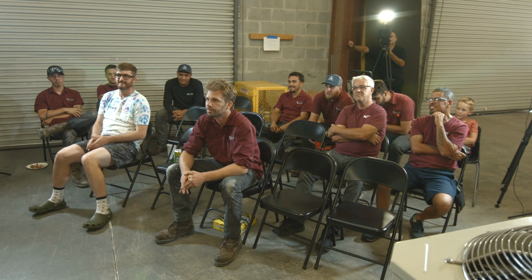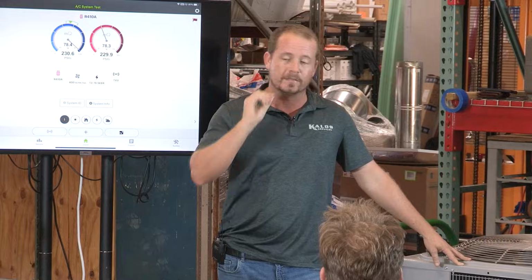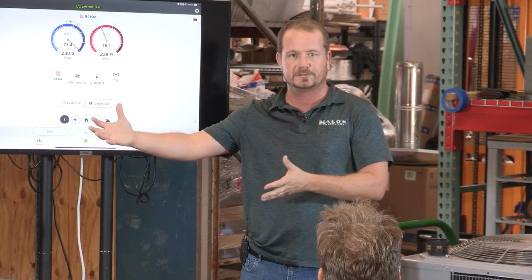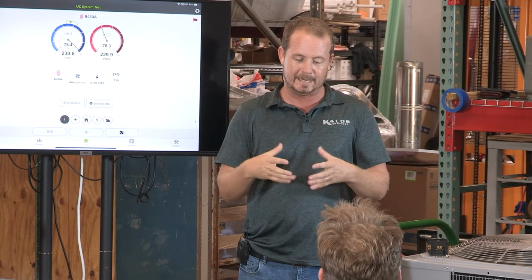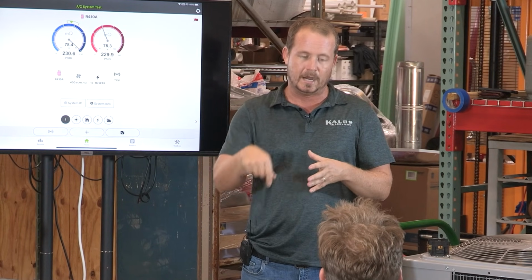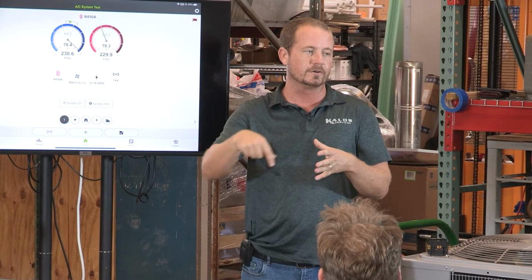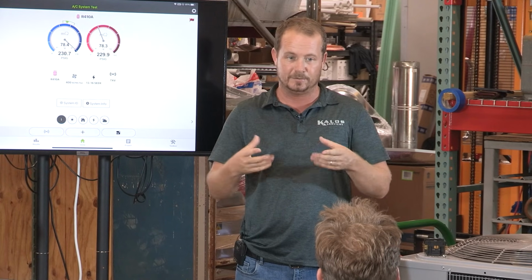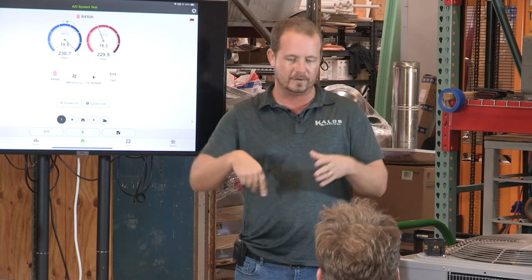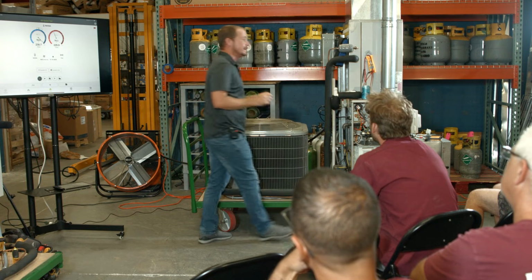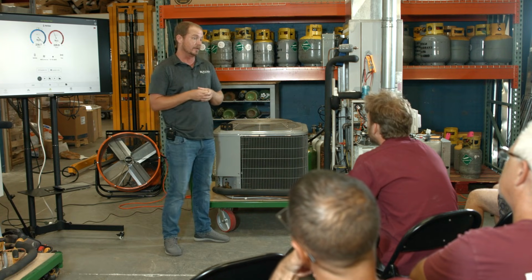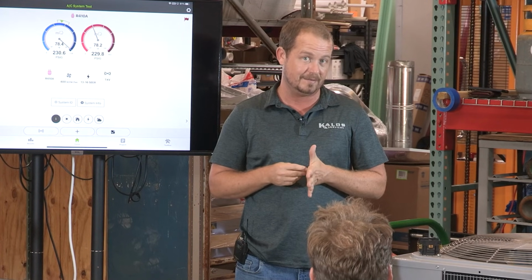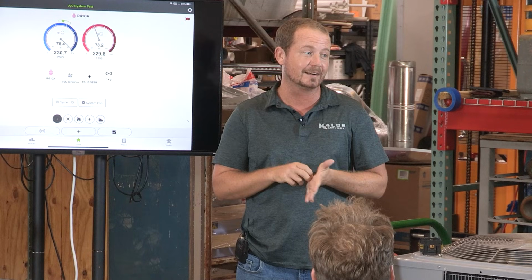Oh, yes. Okay, restriction. Another thing we would do is, if we wanted to force more air, so if we had an area that was getting too much air and we wanted to force it to a master bedroom or something else, we would take a piece of duct board, cut it a little larger than the internal diameter of the flex. We would then cut it in half so it was kind of flexible, and we could fold it over, and then we'd cut a smaller hole on the inside. Now, the trick was knowing how big to cut that smaller hole. And you know what science we used to figure that out? Trial and error. Handometer. Good old handometer, trial and error, yep.